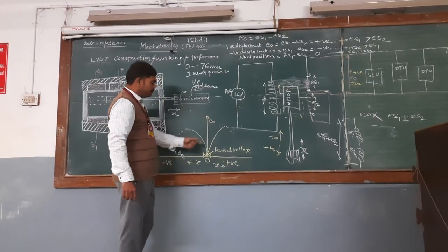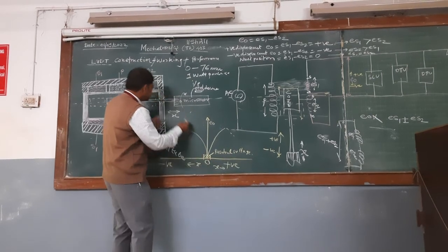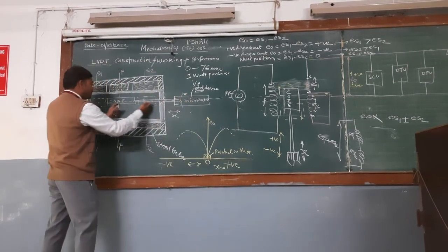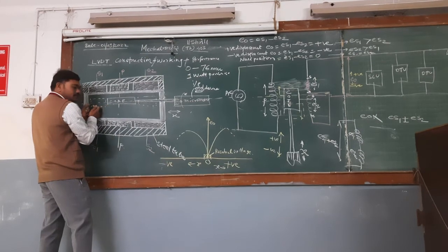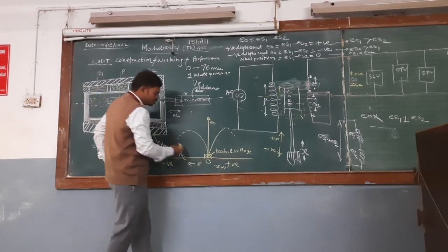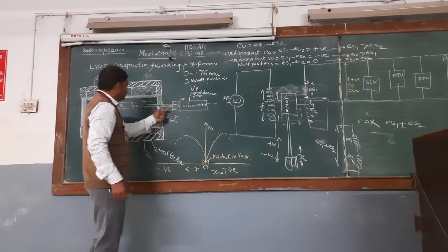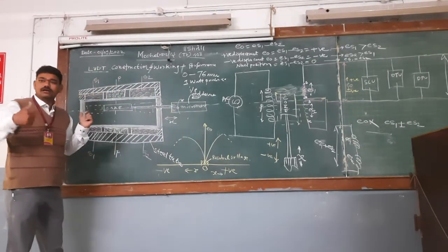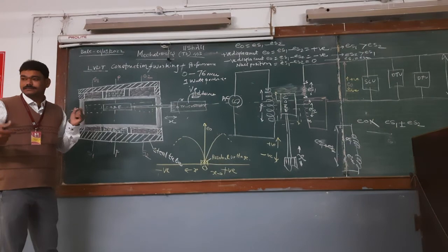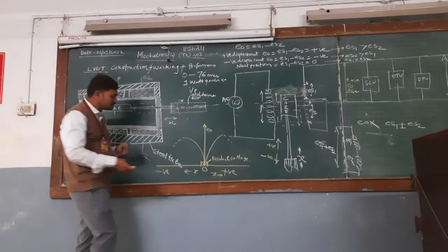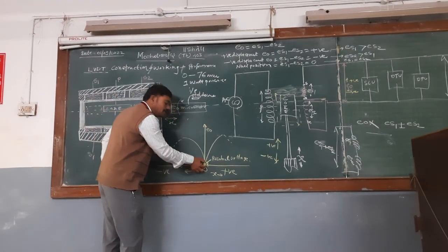Now we know very well, as some input is fed by this micrometer to the core, it will move in the forward direction. Let us consider the forward direction. Initially, as it starts, the output will not show any readings. If it is not showing any reading, it is treated as initial drift.